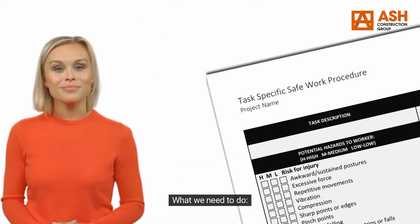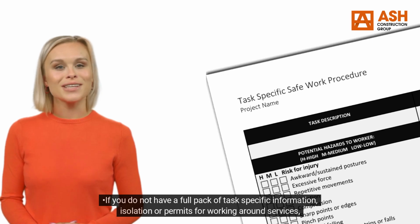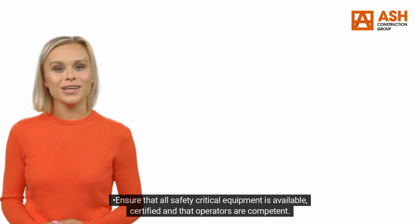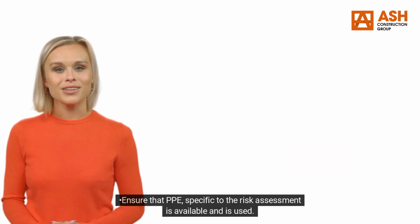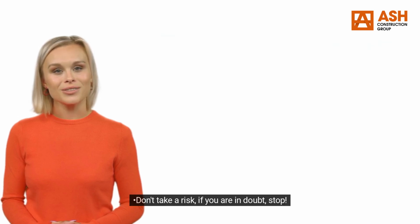What we need to do. If you do not have a full pack of task-specific information, isolation, or permits for working around services, don't start. Ensure that all safety-critical equipment is available, certified, and that operators are competent. Follow the safe system of work at all times and ensure that continual scanning observations are made throughout the task. Ensure that PPE, specific to the risk assessment, is available and is used. Don't take a risk. If you are in doubt, stop.